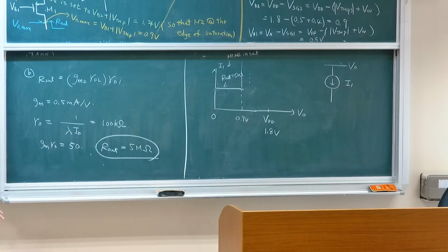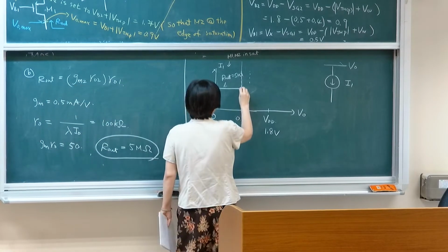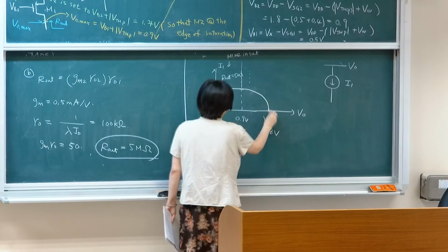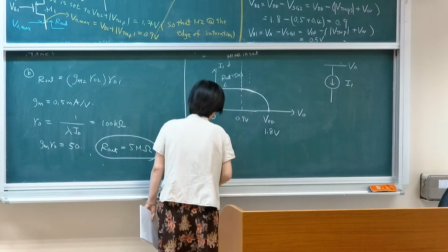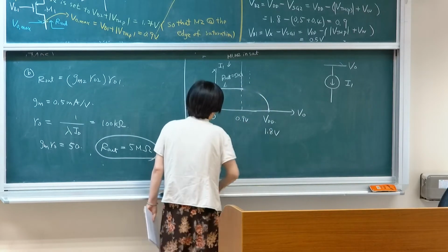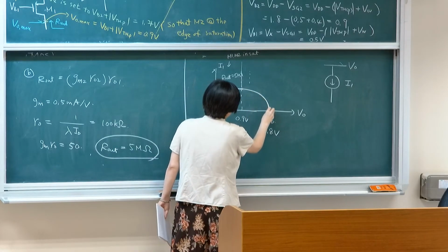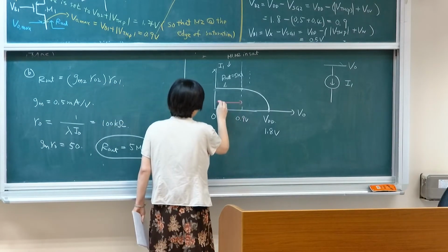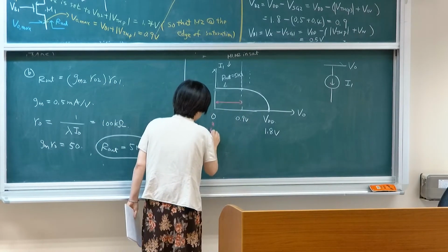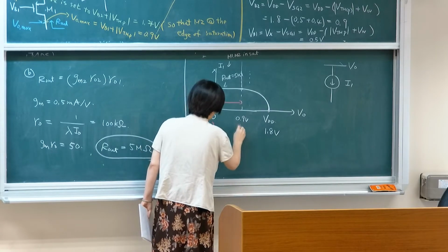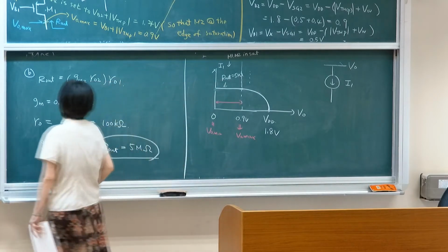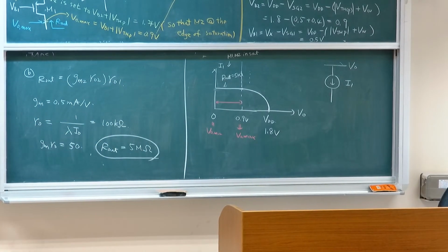When you start to enter higher voltage above 0.9 volt, then either one of the transistors will become linear, so you get degradation of its slope, and then it will look something like this. So you first get sort of degradation in its slope, and then it will go like that. So your operation region is fairly limited. This is VO minimum. This is your VO max. As I said, it's being set by VB2. Okay?